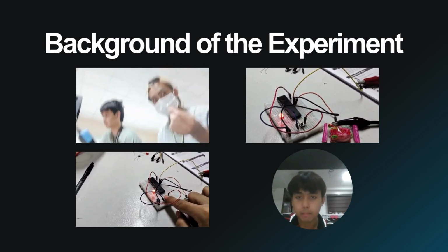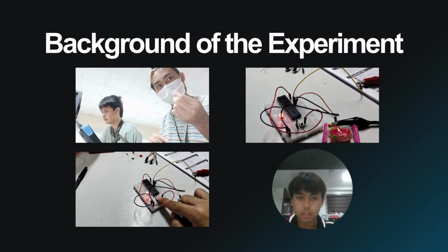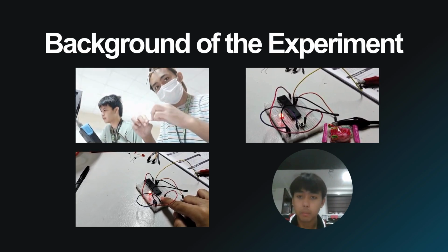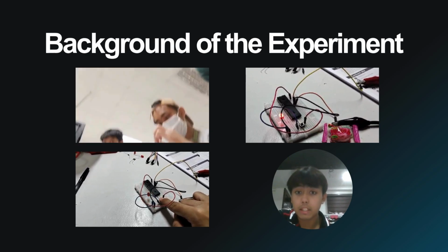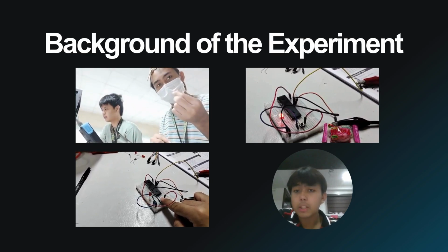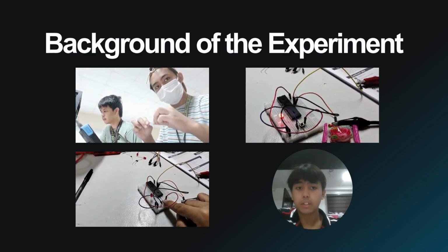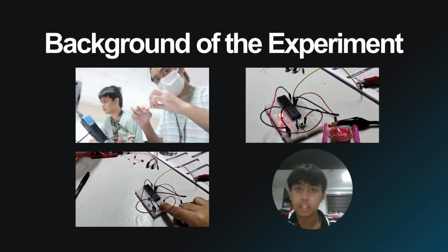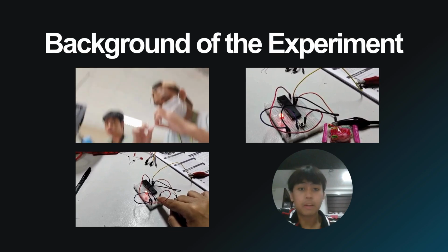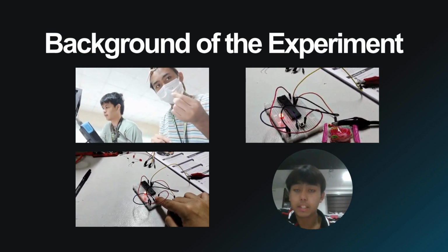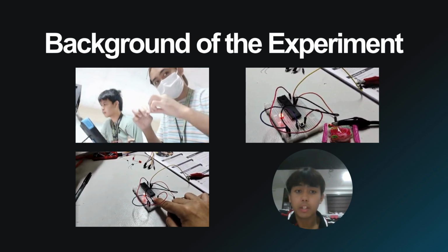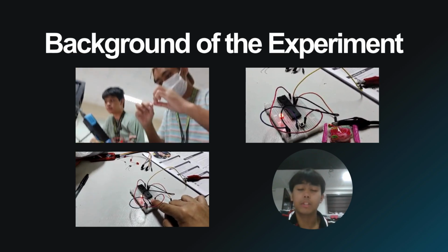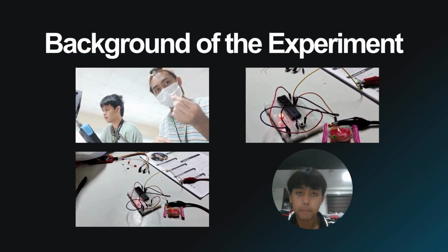Microchip's 8-bit PIC microcontrollers provide a function called timer zero that enables precise timing, which is essential for tasks like controlling communication, producing frequencies, and keeping time. Interrupt on change is a feature in microcontrollers that triggers an interrupt when an input pin changes state. This will allow the microcontroller to quickly react to changes in its environment. Setting up IOC depends on the specific microcontroller, and resources like Microchip's documentation and online tutorials can help.